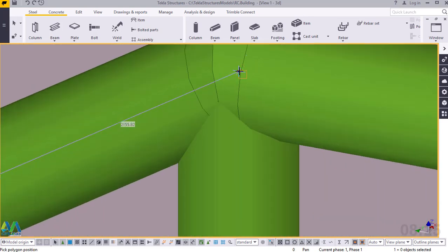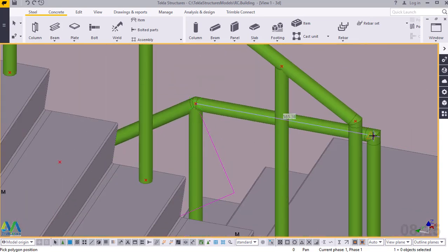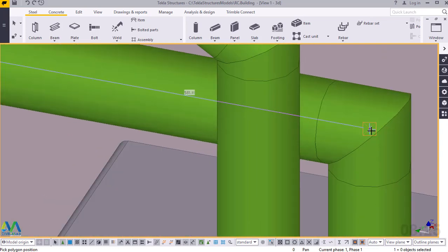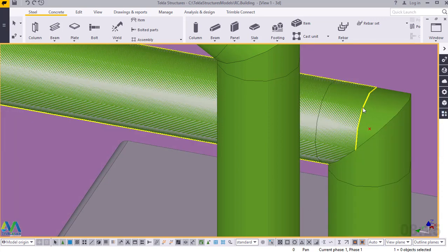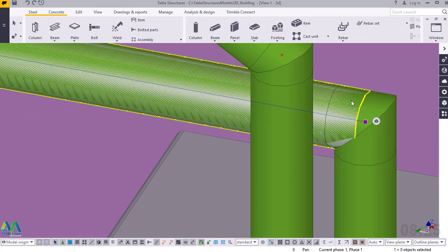and snap right here. Remember, we are doing this manually, so we have control of everything we are doing, and we can place it anywhere and how we want it. That is what we mean by customizing the handrails. Now I'll snap right here. So the moment I've snapped right here, I'll press my middle button on the mouse just to terminate my polygon right there. You can see it has been created, and I'll just click on that, and I will not copy.